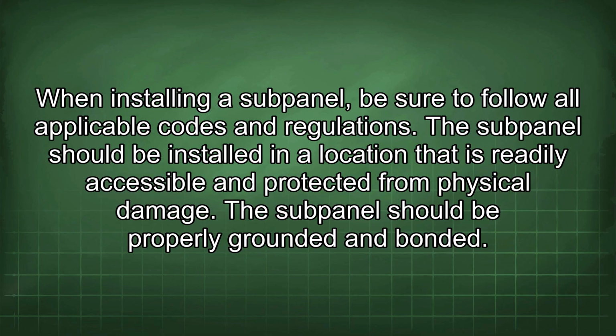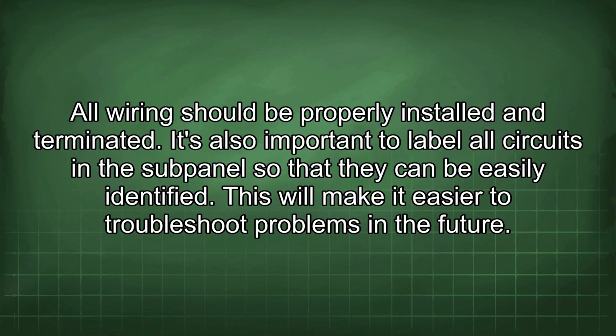When installing a subpanel, be sure to follow all applicable codes and regulations. The subpanel should be installed in a location that is readily accessible and protected from physical damage. The subpanel should be properly grounded and bonded. All wiring should be properly installed and terminated.